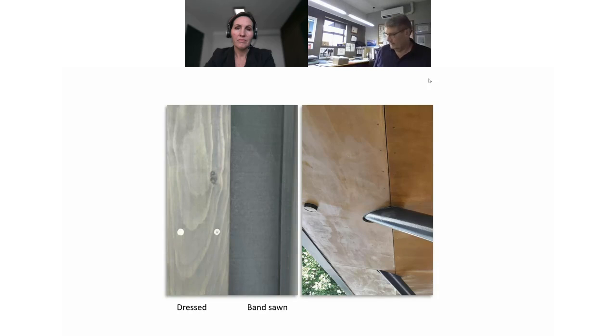And on the right-hand side was a piece of plywood, and the plywood is peeled. So you still get the early wood and late wood bands, which is different density. And you can see there that they used an oil-based stain on there, and it didn't penetrate the late wood, so it's shinier. In the early wood, it penetrated further, so it's duller, and they didn't like that look.